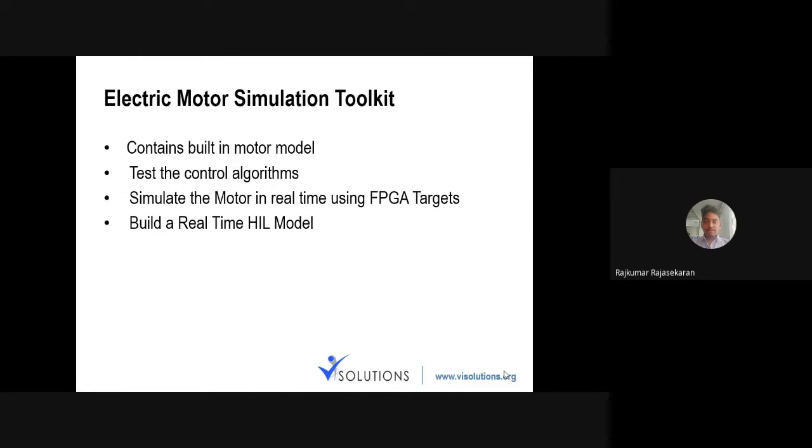You want to test whether that algorithm is working properly before implementing it in an embedded system on a real motor. You could test in these models how it performs in terms of current consumption or whatever parameter you intend to check, and how stable it is. That kind of information you could collect from here. Test the control algorithm.